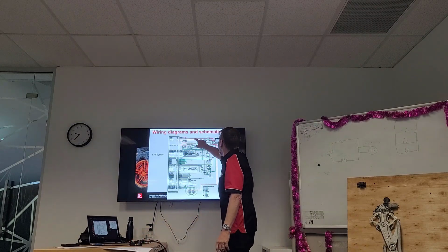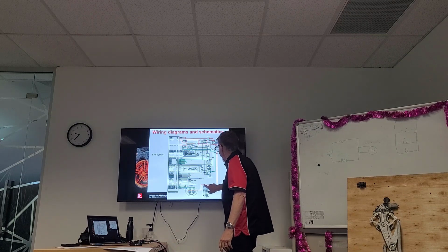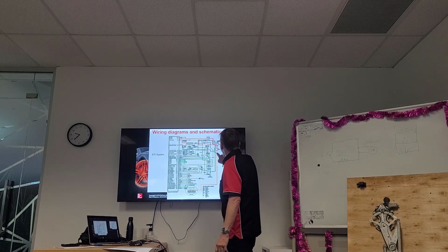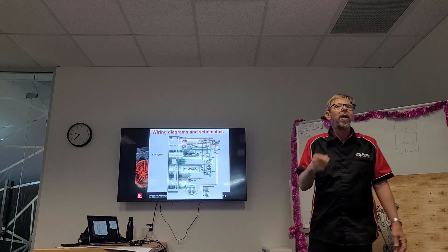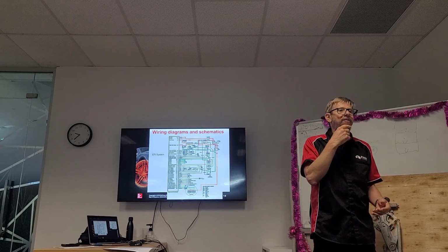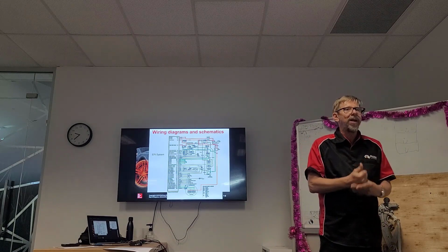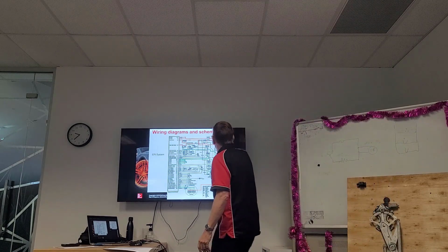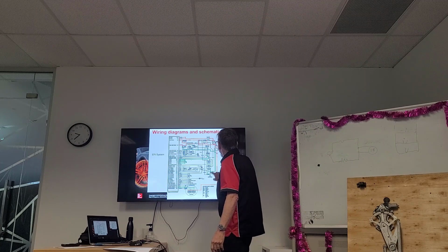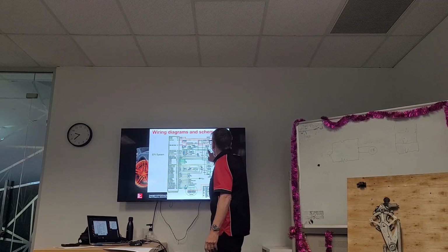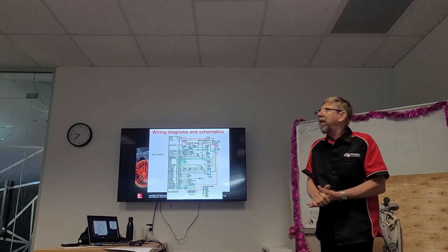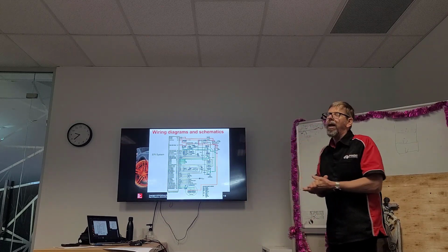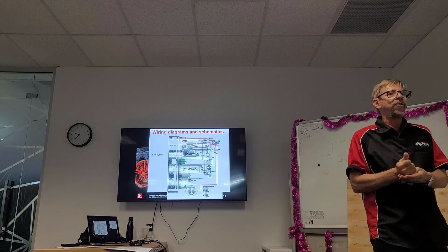See how I've got all the powers in red? Where I've got orange is still power because it's going through a relay. It's transferring power. So when the relay's activated, then those injectors are activated. But that is still a power. And look at the green. Everything's in green. What's green stand for? Ground. Does that look a bit more manageable for us if we see that?